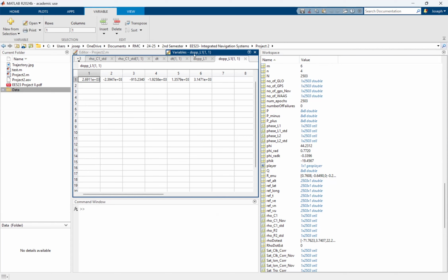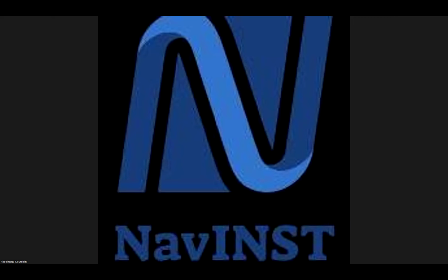And by the way, don't forget when you do the integration, that's a very good question. The uncertainty of the process, the process covariance or noise, the Q matrix, should be scaled by delta T, because your uncertainty after 1 complete second is not the same as after 1 millisecond, right? You are more certain about the state when your estimation is calculated after 1 millisecond.